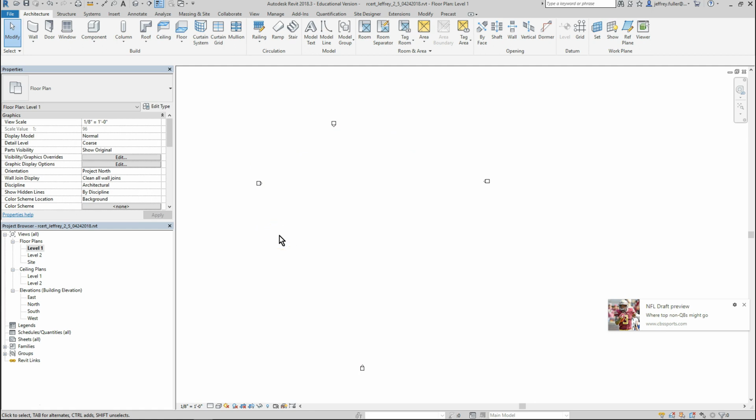Now for creating the first walls. The first method of designing and creating walls is pretty simple because we're going to use the walls that are already in the system. On the ribbon under the Architecture tab, click on the Wall tool.